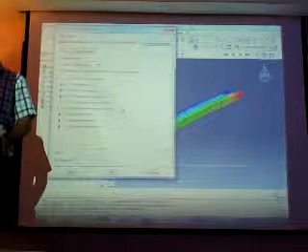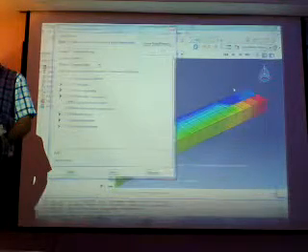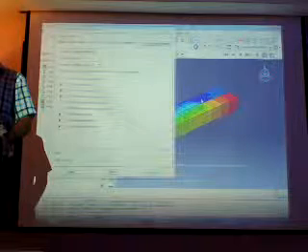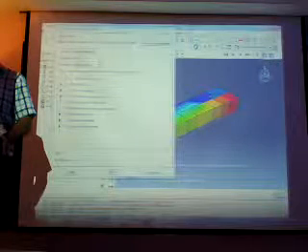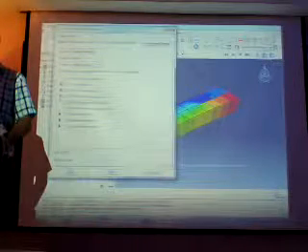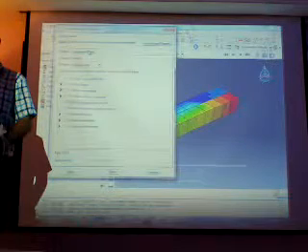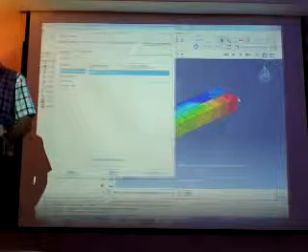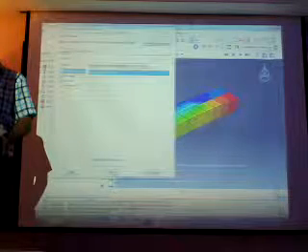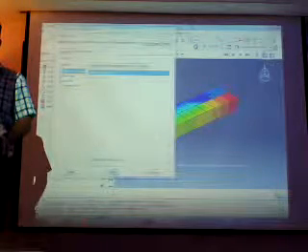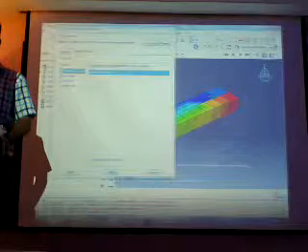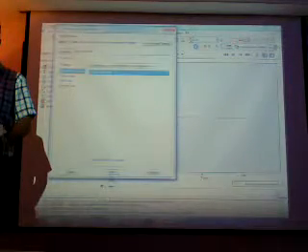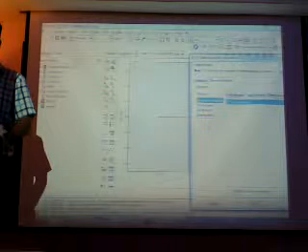For example, we want to see how much is the equivalent plastic strain in this node. So I take this one, and we need to take element, edit section. I take this one down, and we are going to plot the distribution of our strain.